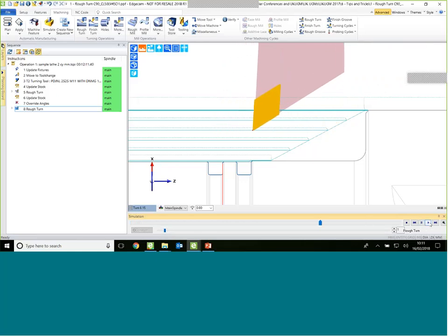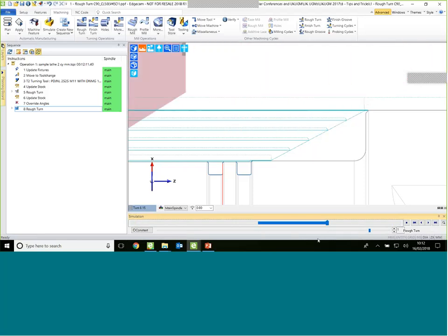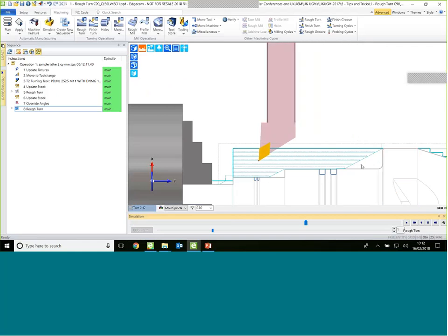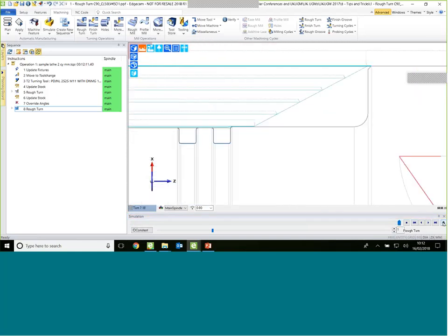Go forwards, go backwards, it doesn't matter how much I play on that particular area, the simulator window is looking purely at that area. So it's shift, drag, that's marking time, then hit the magnifying glass, and it's just going to play just that period, nothing else. And turn it off again.